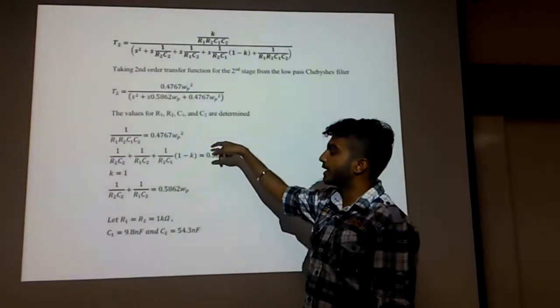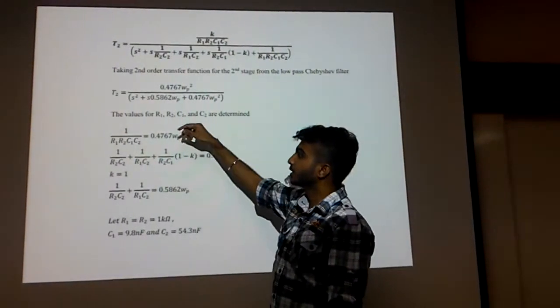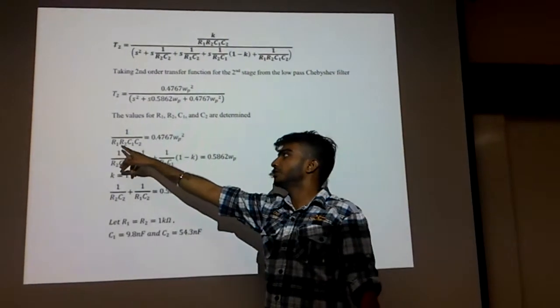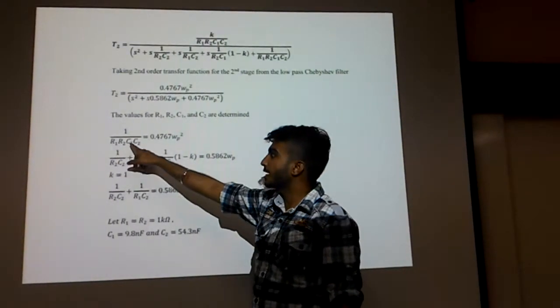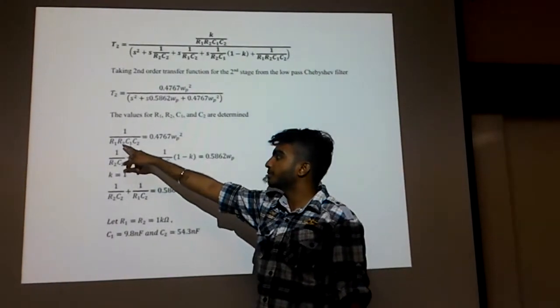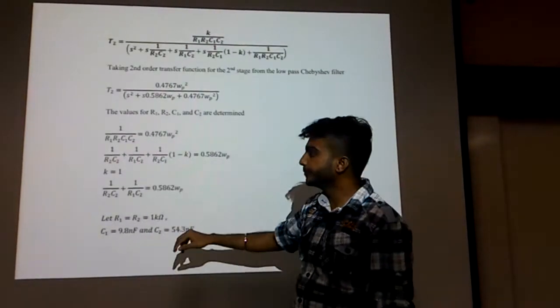So this one was the first order and the other one now is the second order. Second order consists of two capacitors and two resistors. Okay, now we have to substitute again the value. Just now we have assumed R1 is 1 kilo ohms. And now we know that we got some values for C1. We are going to substitute R2 and C2 because it's now unknown value.